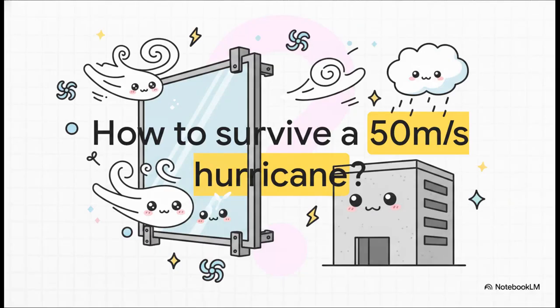Well, it all starts with understanding our invisible enemy. Wind is a dynamic, constantly fluctuating force. You see, unlike the heavy concrete and steel of the primary building frame, which are mostly just fighting gravity, a curtain wall is basically a giant sail. Because it's this huge, lightweight, and incredibly flexible surface directly exposed to the elements, wind pressure, not dead load, is almost always the governing structural design load we have to beat.